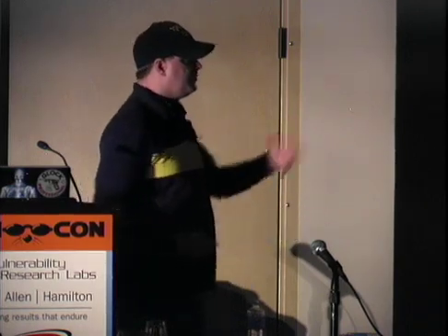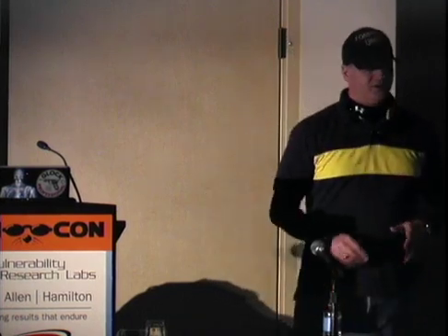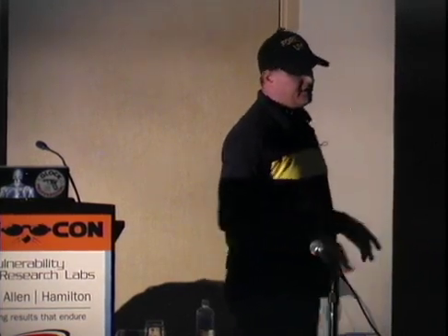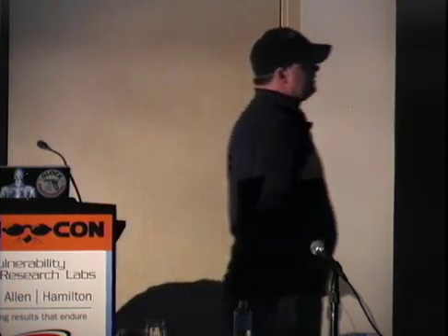But at the same time, you may get even condensation or temperature changes that may do damage to it. So if you're lucky enough to get it to work and you're going to do that on your own, you got like 10 minutes maybe before the drive might die again and you're done. So if you're going to try that as a last resort, great, but it is not a great diagnostics process to just like throw it in the freezer and hope that it's going to work when you're done. But if you got nothing else, I just don't approve of it.